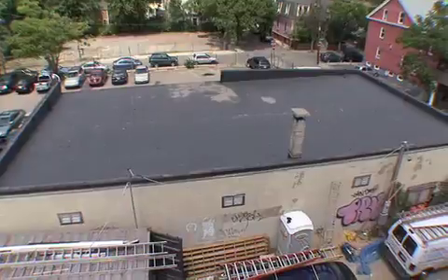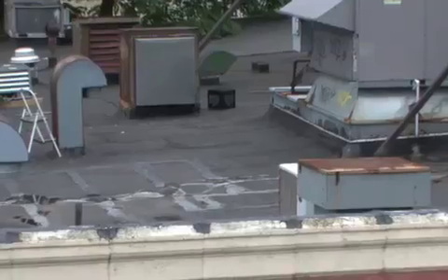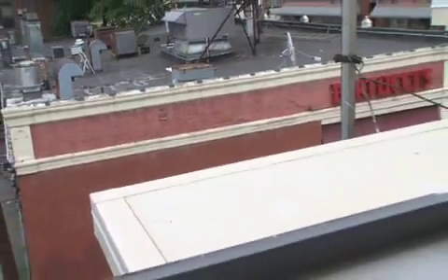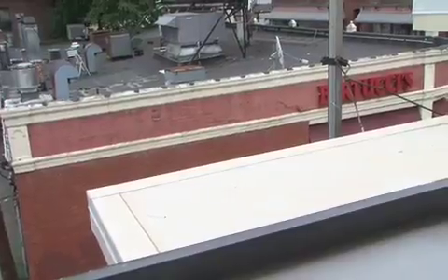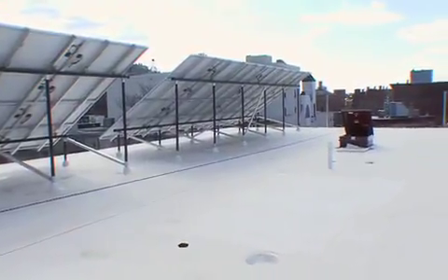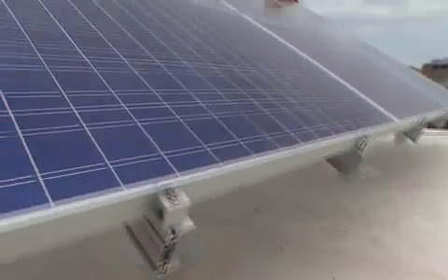Reducing the effect of radiation on a surface, such as a roof, can be as simple as changing its color. Radiation from the sun hits the roof. When it's a black roof, there's a portion of it reflected, but it's very little, and the amount of heat that gets conducted into the building is much higher. Whereas when you have a white roof, a lot of the heat is reflected back, and then that portion of the heat that gets conducted into the building is much less.